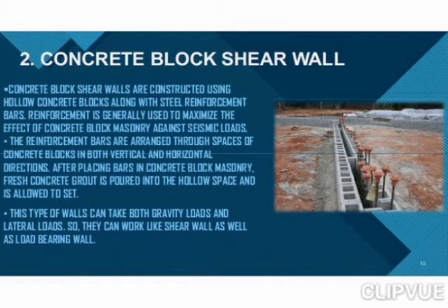After placing bars in concrete block masonry, fresh concrete grout is poured into the hollow space and is allowed to set. This type of wall can take both gravity loads and lateral loads, so it can work like a shear wall as well as a load-bearing wall.